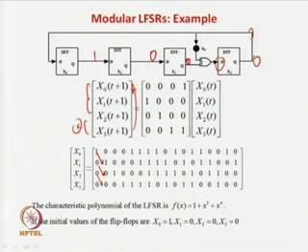So, to determine the value of x3 we have to XOR 0 with this XOR. So, 0 XOR 0 is already a 0. So, we get a 0 over here, and you should also know that x3 will directly control x0. So, this value will go over here. So, very easily we can get the vector 0 1 0 0. These two are direct controls, with no dependency, and x2 is controlling x3, but with an XOR with this one. So, 0 XOR 0 gives a 0, and this one will be directly feedback over here. So, we get 0 1 0 0.